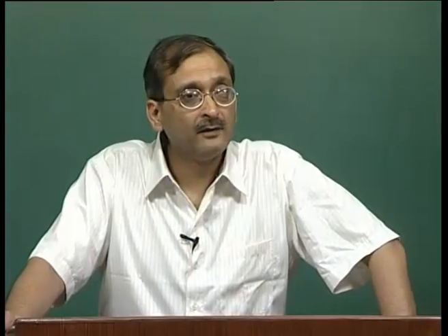For n is equal to 3, we have n times d or 3 times d. Let us say d was 3 hours, and if n is equal to 3, this rainfall is occurring in 3 plus 3 plus 3, 9 hours. All right. So, we have a DRH which results from 3 centimeter of rainfall, which occurs uniformly over the whole catchment in 9 hours.